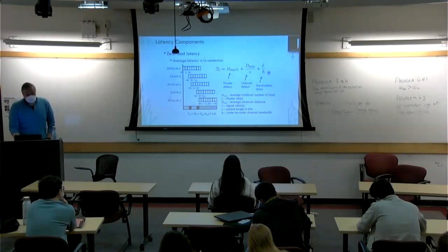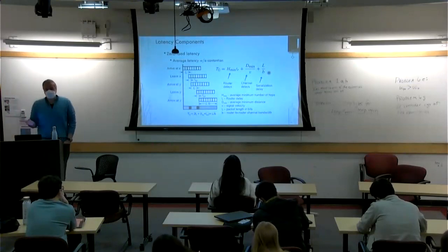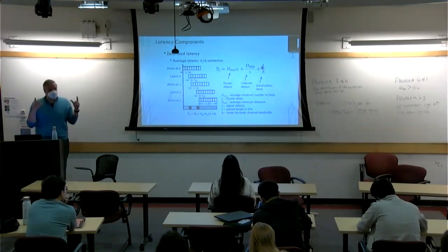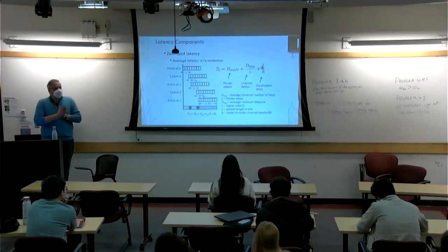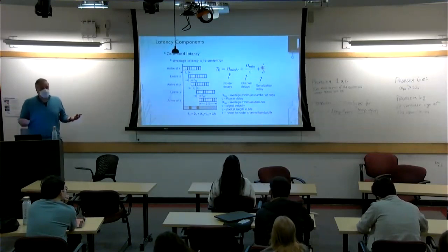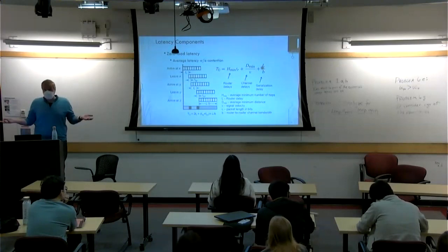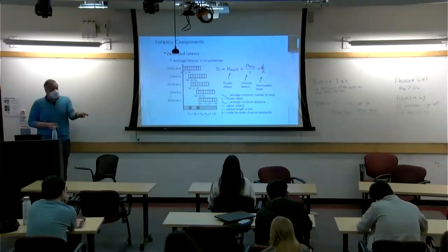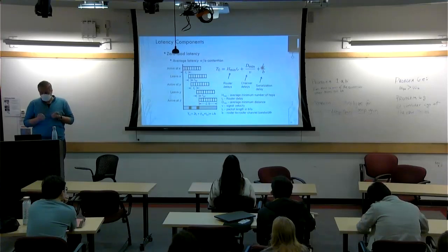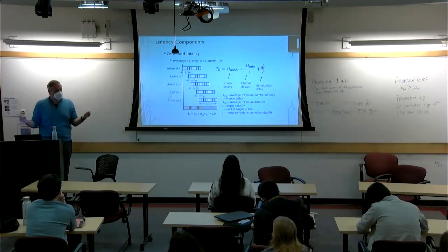And then the last component here is what we call serialization delay. This serialization delay is basically the length of that unit that you're sending, L, over the bandwidth. And bandwidth we express here as, let's say, bits per cycle or bits per second, whatever you want, right? So here is why this partitioning into smaller things matters, right? If your message is long, let's say you decided to stay at 64-bit flit size, right?